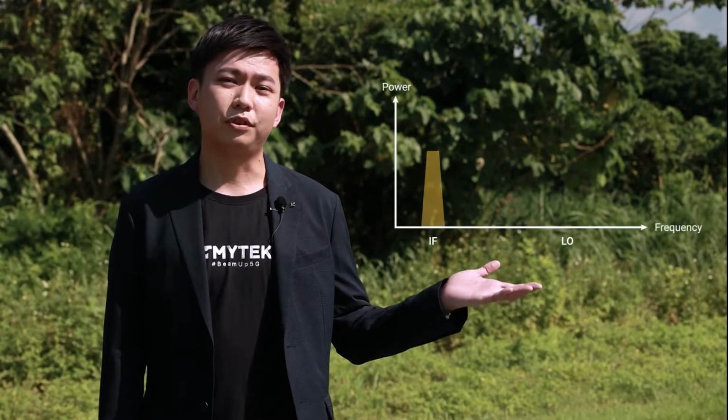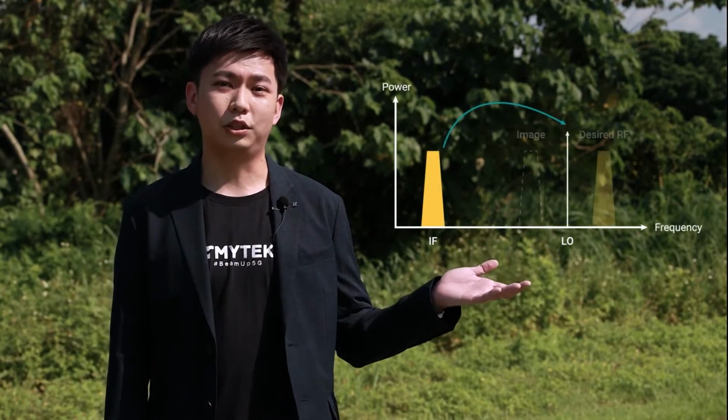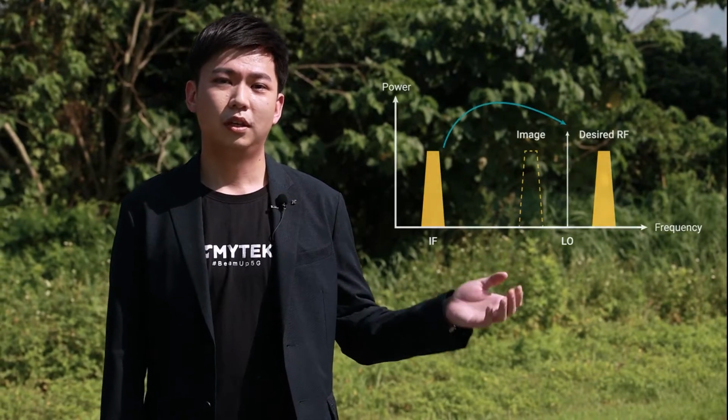On the other hand, frequency conversion is a complex issue that you have to take into consideration. There are two main parts of frequency conversion, which are the local oscillator and the frequency converter. The most difficult thing is how to develop a good frequency conversion device. You have to pay attention to LO's quality, such as phase noise, harmonics, even the driving power of your frequency converter. Otherwise, control interface, synchronization, and regarding accessories are the things you have to pay attention to as well.